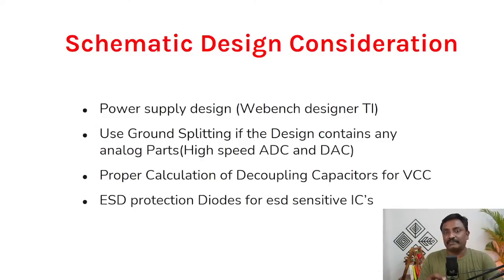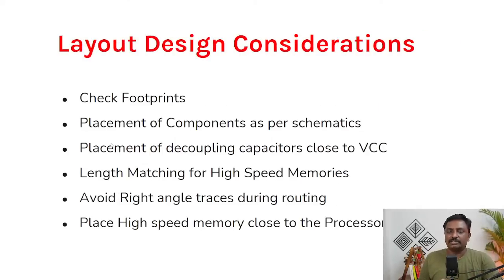Whenever you connect the microcontroller with the outside world, you need these protection diodes to protect the IC. Otherwise the IC will get damaged. So these are the schematic design considerations. Layout design consideration is to check the footprint size and placement of components as per the schematics. I'll explain how to place the components as per the schematics in the PCB design session.